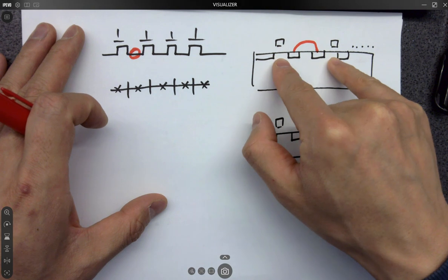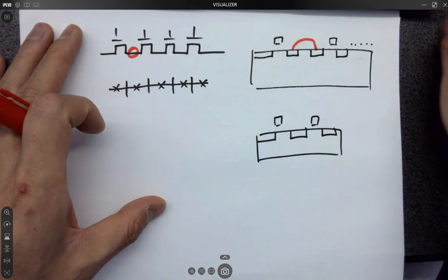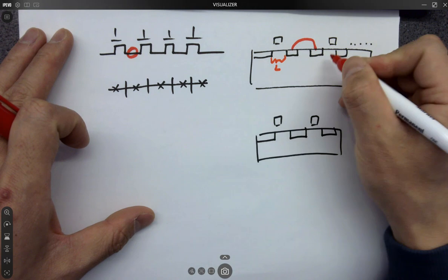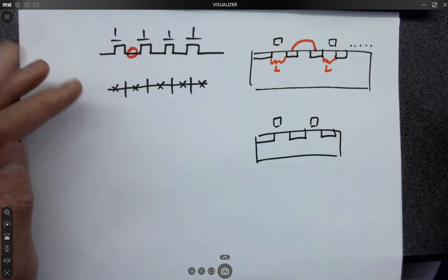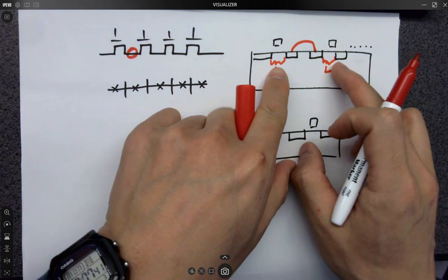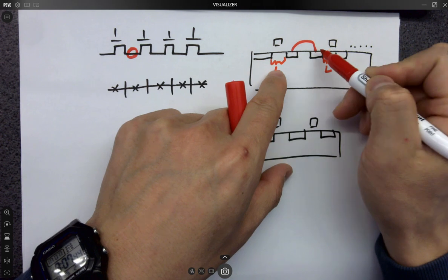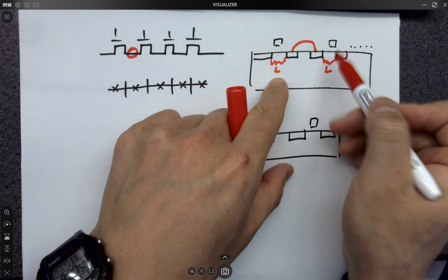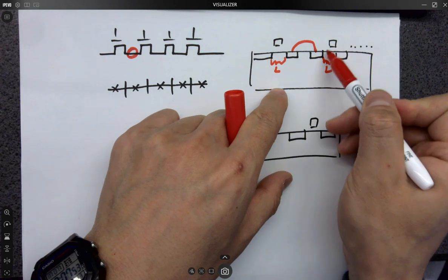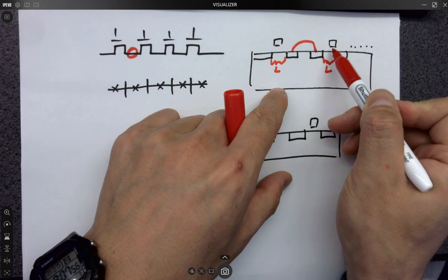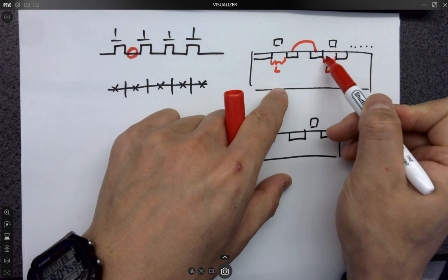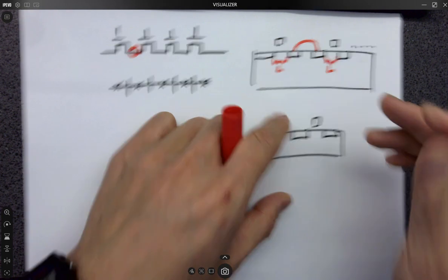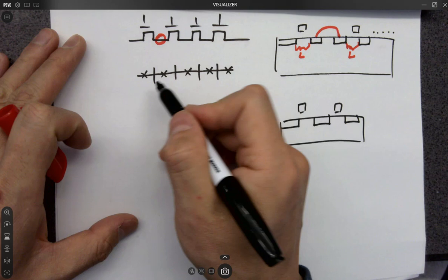And why is this two channels, 2 length? It's definitely longer than 2 length, right? What is the length of the transistor? Which dimension is the length? Here's the length, right? And when you are putting them in series, it's adding the length together. And these are not considered as length of the channel because these are just the wires. So we only consider this part as the length, which is exactly the area underneath the gate. Because only the area underneath the gate is considered as a channel. Okay, but all these are just wires. So in that case, you don't even need all these gates.